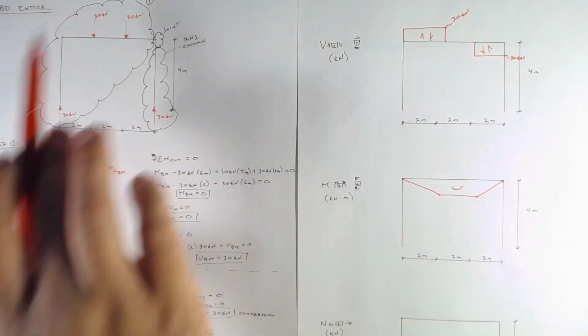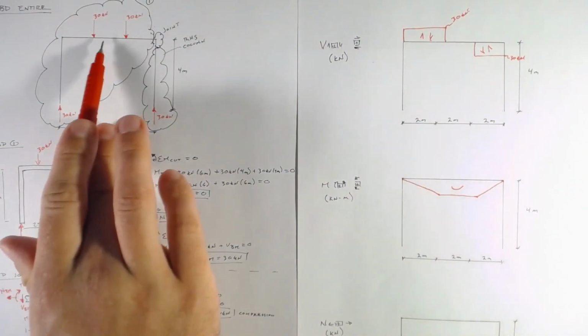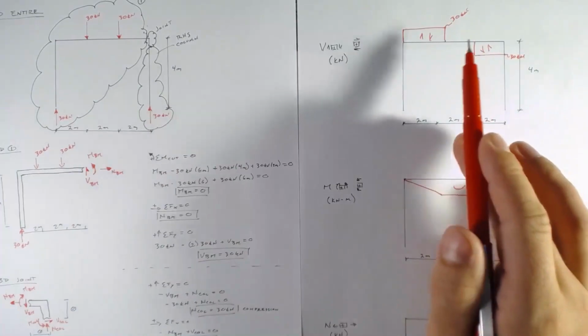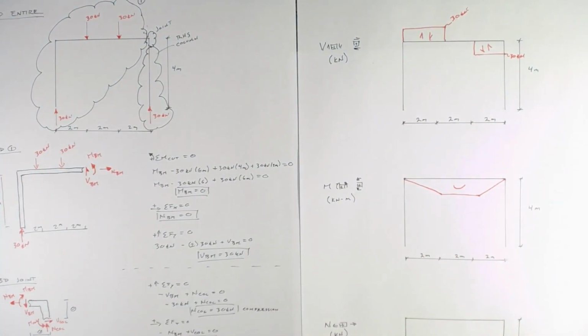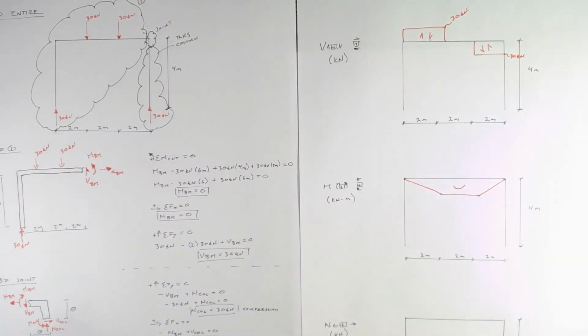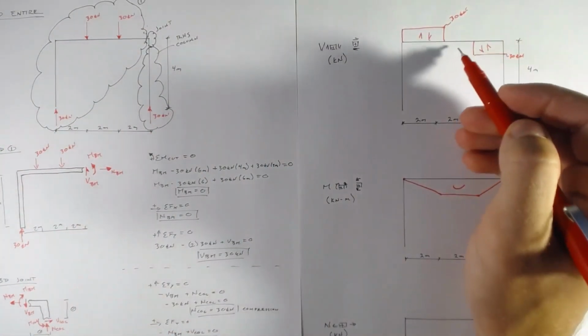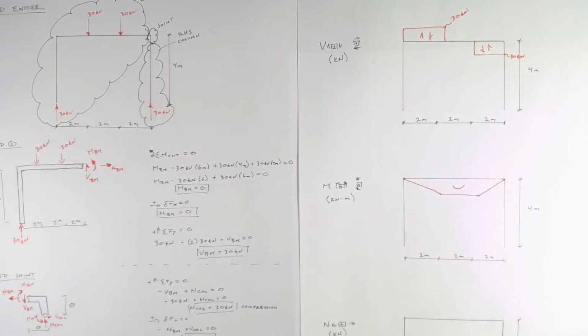Now, some interesting things to note here. When you have this what we call 4-point loading, where you have 2 points pushing down and then the 2 points at the reaction, in the middle here, if these two are equal, then we have no shear force and we have a constant moment. We can use that to our advantage. If we have this beam and we need to put a hole in it, we might put a hole right here in the middle where the shear force is quite low. You'll learn more about that as we go through this course, but it's just a nice, interesting thing to know.